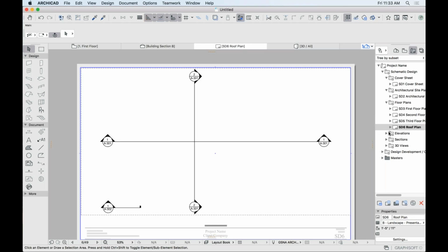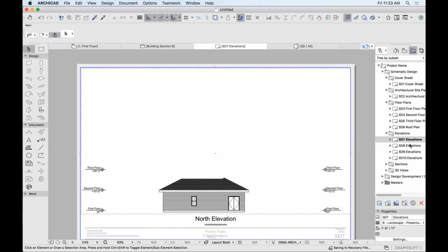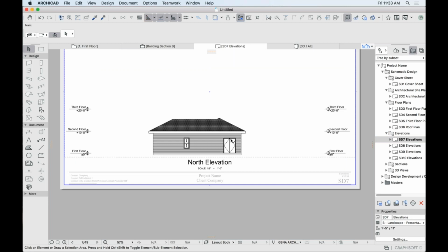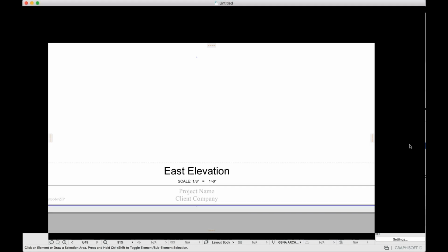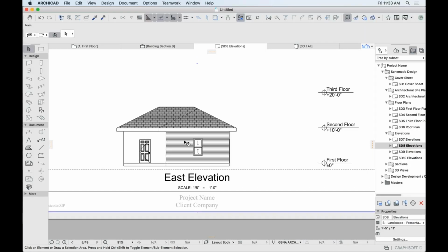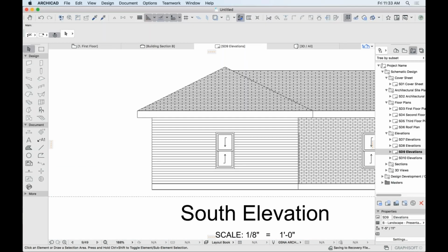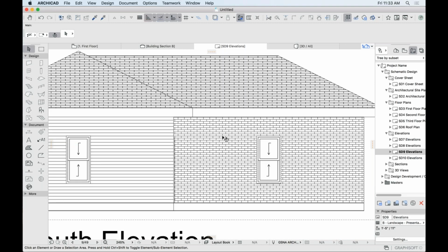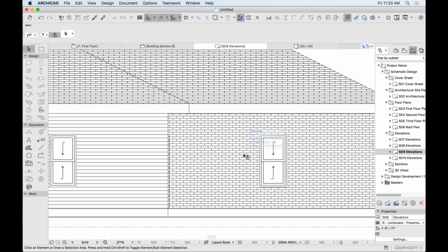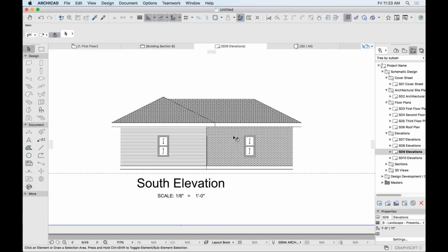Now let's see. I guess I don't have anything on my 3rd or 4th story, so that's why that's coming in that way. But you can see that these drawings are already being generated from that quick little building I had made, and it applies the hatching effects that are relevant to a drawing. So that was that blue wall with no siding. And then here we should find the brick pattern as well. So it reflects properly on a printed sheet based on a set of rules.